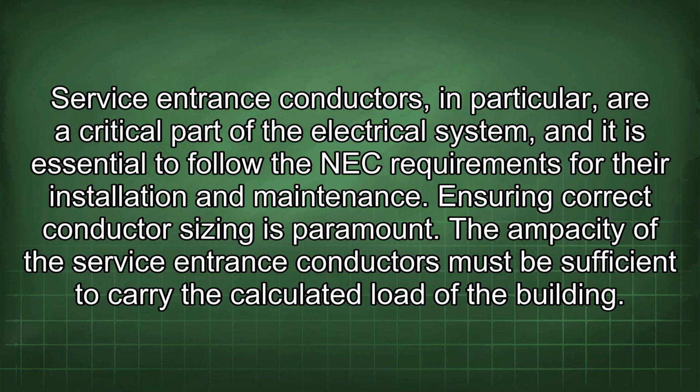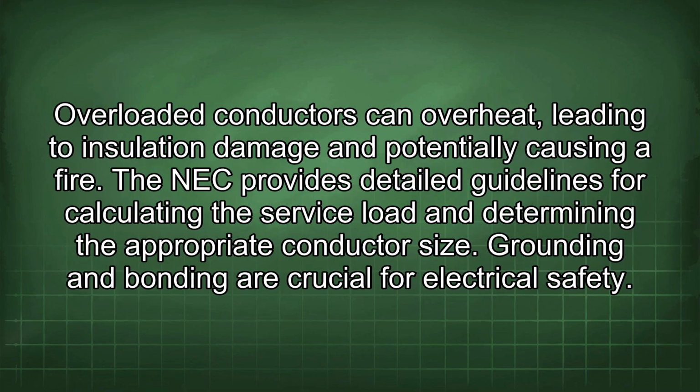Ensuring correct conductor sizing is paramount. The ampacity of the service entrance conductors must be sufficient to carry the calculated load of the building. Overloaded conductors can overheat, leading to insulation damage and potentially causing a fire. The NEC provides detailed guidelines for calculating the service load and determining the appropriate conductor size.